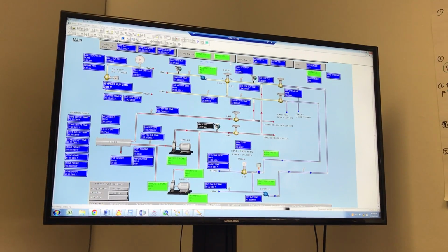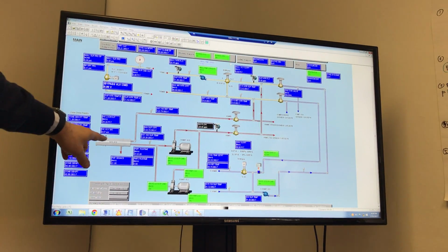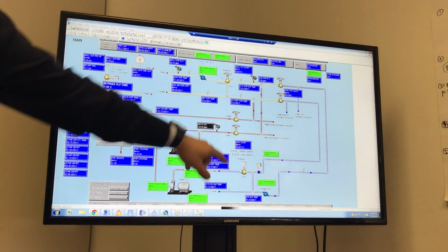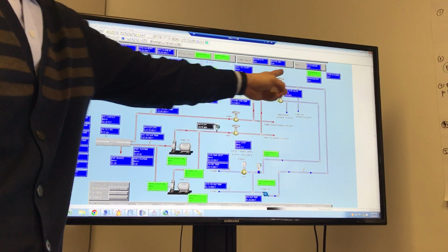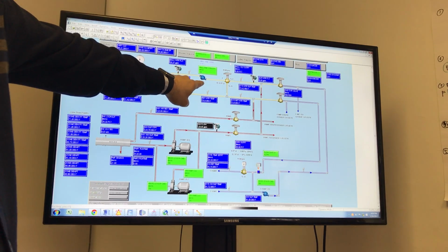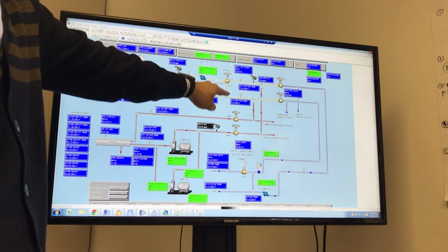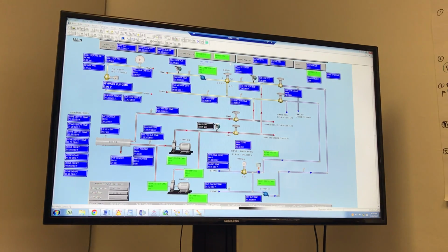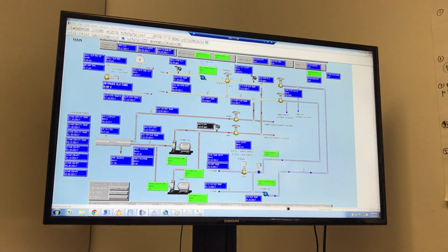Is this the whole IW? No, this includes the IW part and the stuff in the basement. Basically the heat exchanger, the pumps. There is another pump in the basement. This is the cooling loop and the heating loop. These are the valves. This is the booster pump we saw in the mechanical room just before. And these are the pumps enabling the recirculation, and the change between the hot water loop and chilled water loop.